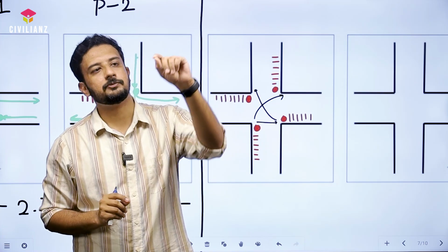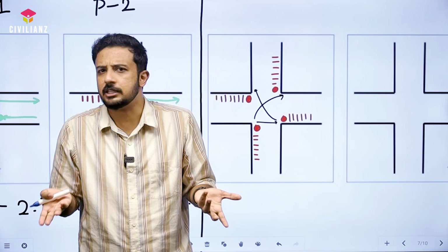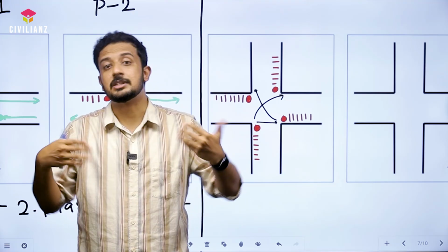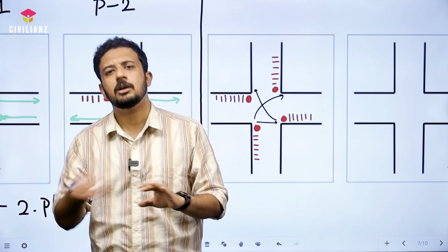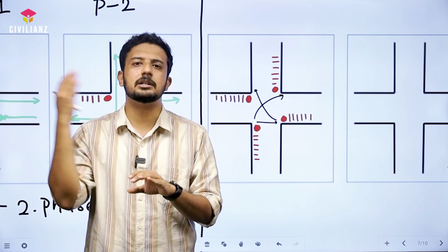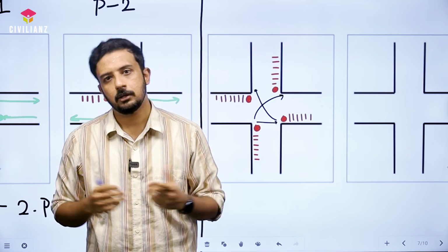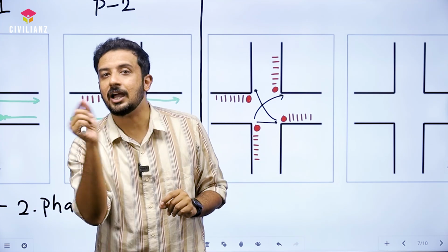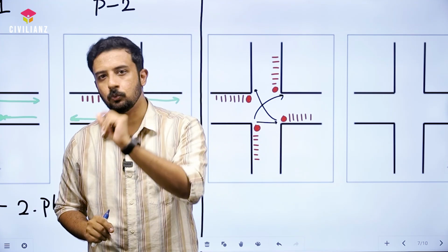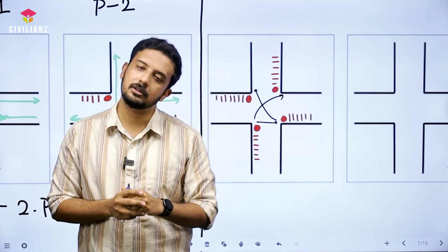So obviously the normal flow to saturation flow ratio will be less than 1, because saturation flow is an ideal concept. Without any interruption, what can be the maximum number of vehicles that can go in 1 hour? Definitely higher than normal flow, no? That's why I told you small y values will always be less than 1. Get the concept now?